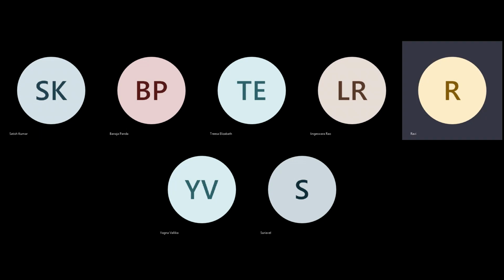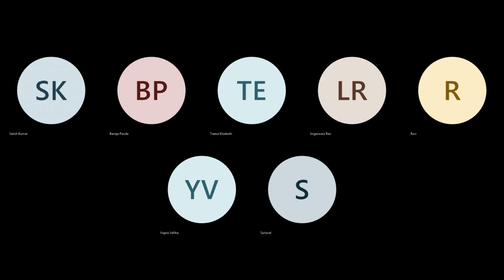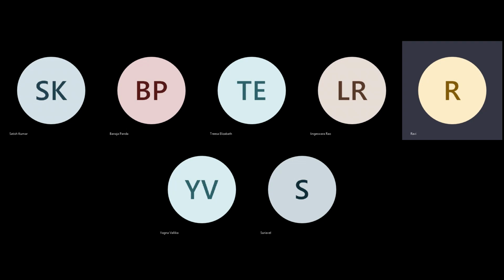So that's what is expected. At an engineer level you may not know, you're new to certain things, but this is what we have to do. Floor plan has to be done manually because, from an architecture point of view, memory is placed first, and once you place the memory, it becomes a critical initial point for the standard cells to place. They will look at the route length with the memory placed and fixed. That's why you have to fix it. You cannot keep it unfixed, floating. Then you are not doing the right thing.